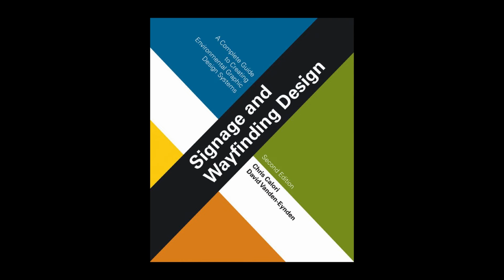Typical metals used for signage include aluminum, used for sign faces, plaques, cladding, trim, and lightweight to medium weight structures, as well as for castings. Considered one of the white metals, aluminum is a lighter shade of gray than stainless steel. Other characteristics include good appearance, good durability, lightweight, and medium to high expense. Aluminum also typically benefits from clear or opaque protective coatings, although such coatings are not necessarily required. See Figure 6.36.